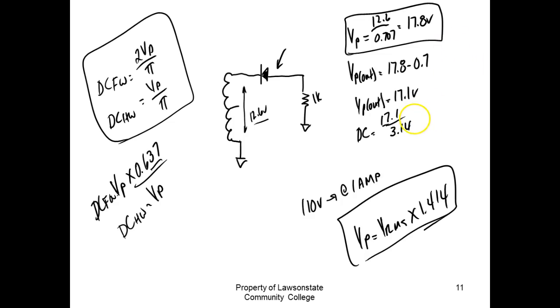So what do we get here? V peak over pi, since it's half wave, or 5.45, which rounds up to 5.5. And I think we measured 6.2, so that was within 700 millivolts of what we calculated, just using all the specifications that were given to us.